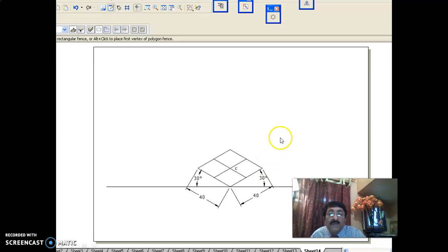Then, as you are aware, the height of the pyramid axis will be parallel to the vertical edges. In that way, you should clearly know the axis is isometric, the base edges are isometric, but the slant edges are non-isometric. Non-isometric edges cannot be drawn by you. You should concentrate only on isometric edges and manage the objects.